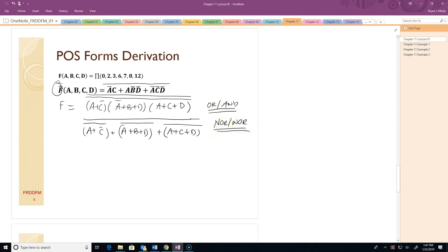You do see it occasionally here. So what I have is two terms being ORed together with an overbar. That makes it a NOR. Same here, a bunch of terms being ORed together, overbar, another one here. But in the end, I have 1, 2, 3 terms being ORed together with a giant overbar. That's your outside NOR. So this is a classic NOR form. Okay, next step is to bring this overbar down, and I'm going to do this.